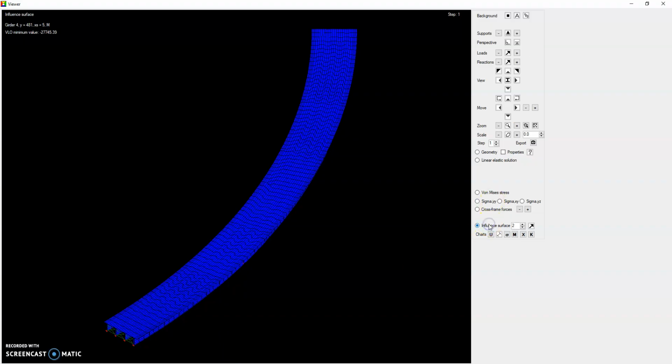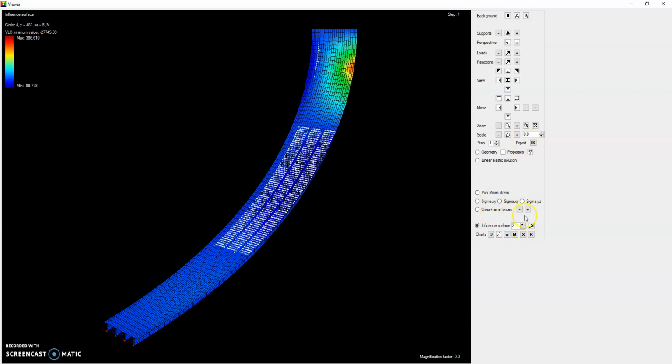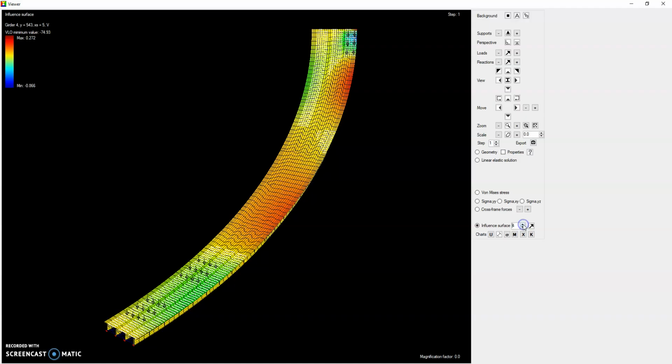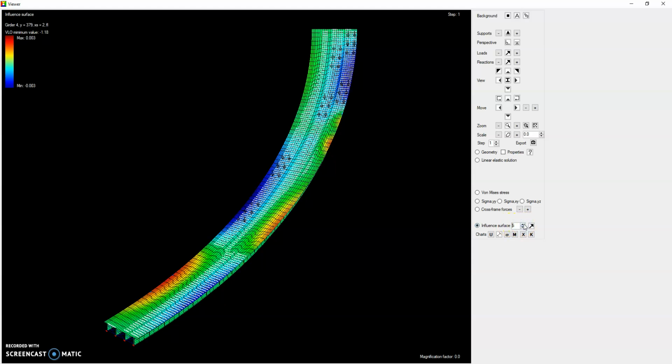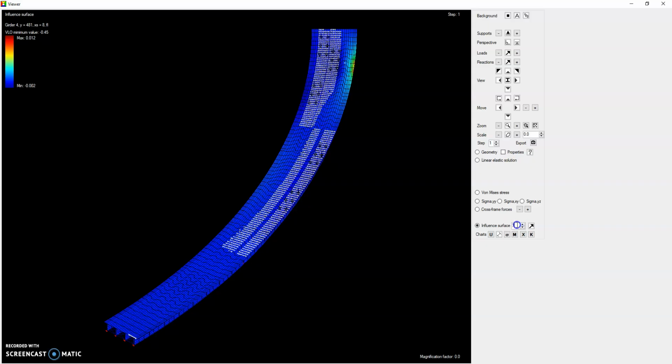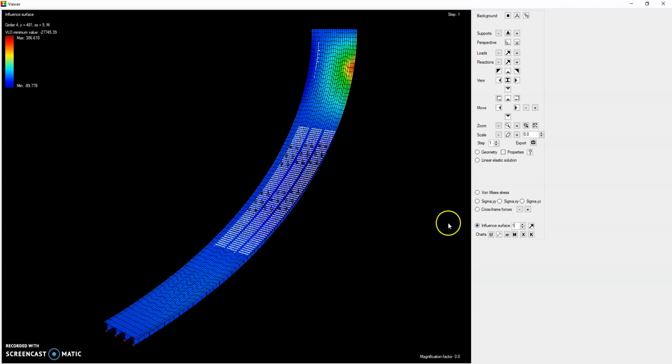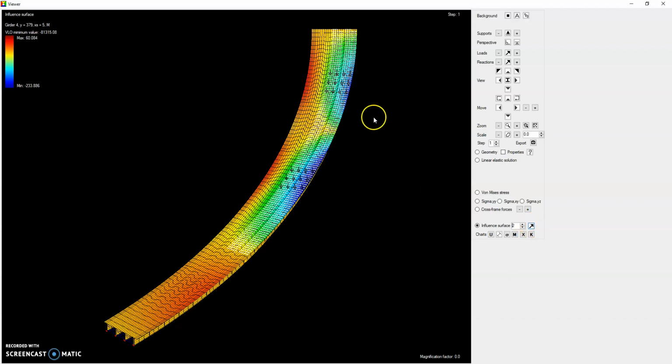Of course, you will need influence surfaces for all that. So this will be, for example, the influence surface for different limit states here. This is extremely important for you to consider in your design. In this case, we're going to look in particular at negative bending at the pier. So we need to select the right influence surface, which is this one. And you can see this is the dual truck, which is positioned on each of the 2 lanes. Thank you very much.